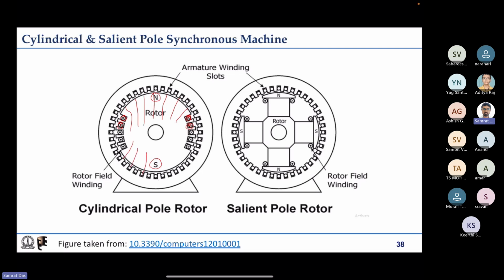This is how they complete their path. All these are closed lines, of course. This is how the rotor magnetic field would look. And if the rotor is made to rotate, we would be able to produce a rotating magnetic field running at the same speed as the stator magnetic field.